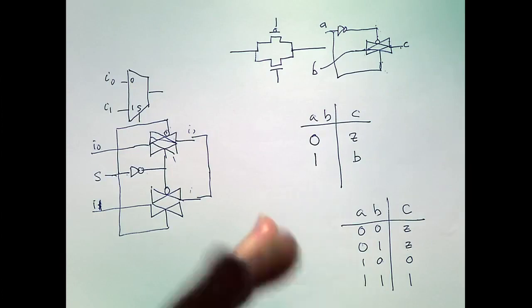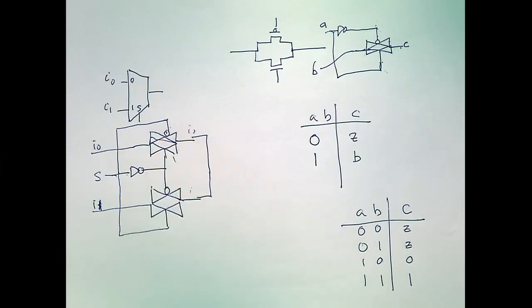When you wrote your Verilog code in Vivado, you were not allowed to tie 2 outputs together. What happened when you did that? Yeah, you got the multiple driven net, right? You don't want to do that in an FPGA because then you're trying to drive an output both high and low, and you have basically a short.